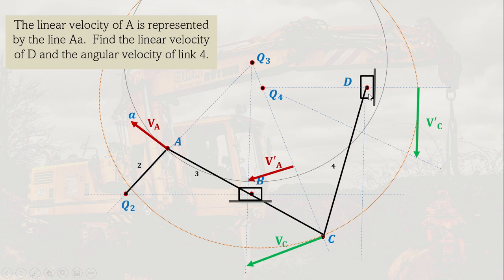and then since we know that the direction of D is in this direction, it's obvious to us now that the velocity of D would be the intersection. So this is the velocity of D. As you can see, it's proportional.